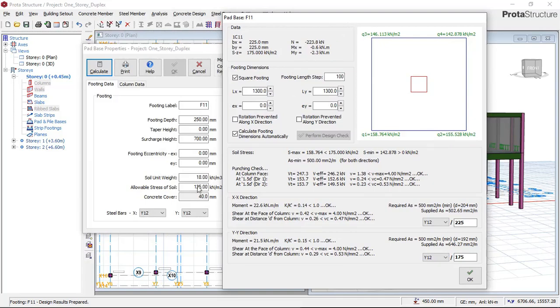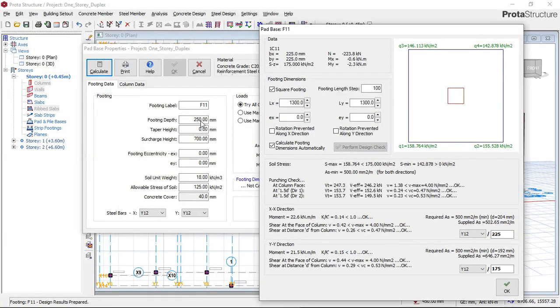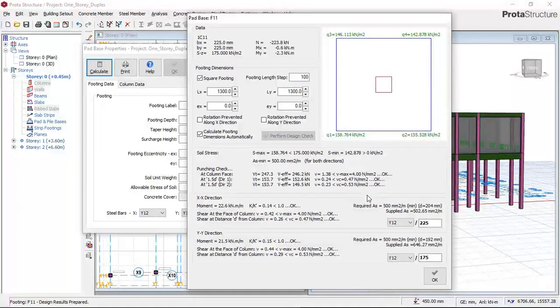Don't go and decrease the bearing capacity, because the bearing capacity is what will carry the structure. All you have to do is increase your depth of footing. And if you have increased your depth of footing to at least 500 millimeter and the footing is still failing, at that point you must change your choice of foundation from pad foundation to either strip foundation or raft foundation.